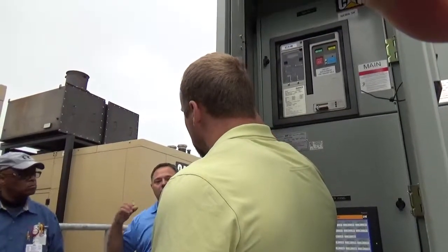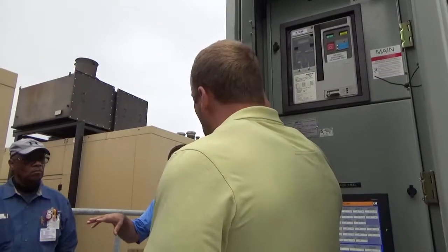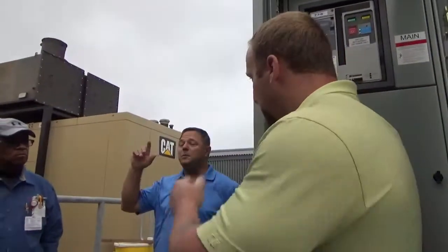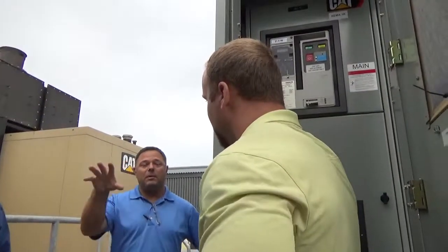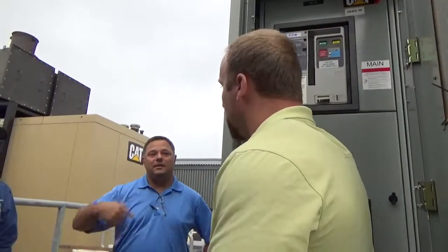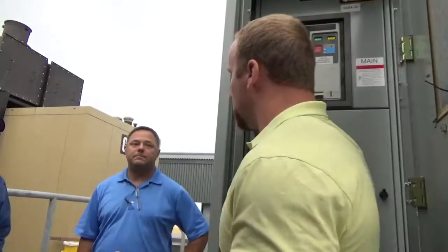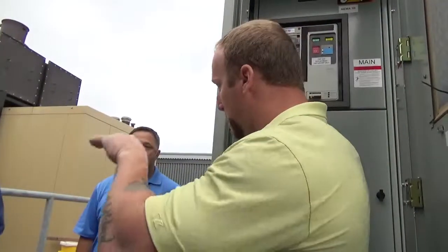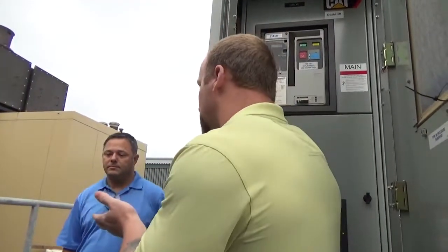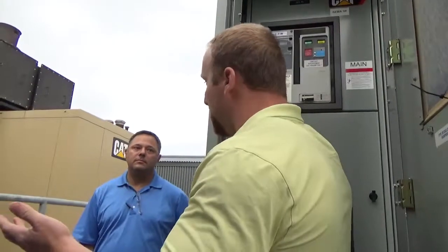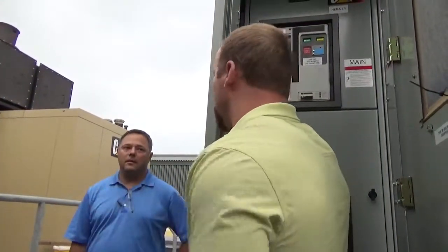Each generator, will the load immediately go to just one, or will it always split them? It always splits. So then, basically, both of these are going to sit with nothing on them until someone gets here, because we probably won't have the load bank set. Right, because this is a manual one. You have to come out here, put on the amount of loads you're going to want, and you have to know what your site load is going to be when you put it all on the generator, and then you can come out here and go, this is how much I want every single time that it comes on.